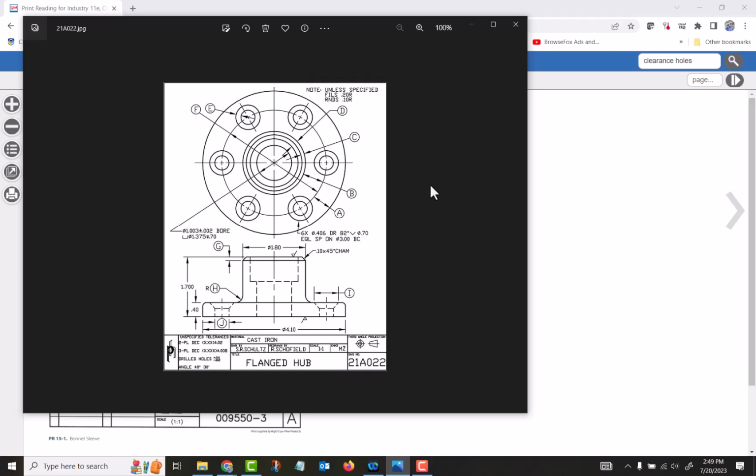When it comes to castings, typically you have an 1/8 of an inch additional material on each surface that would be machined. So we look at this part right here, and it has a total machined height of 1.7 inches. There's a finish mark on the bottom and a finish mark on the top here.